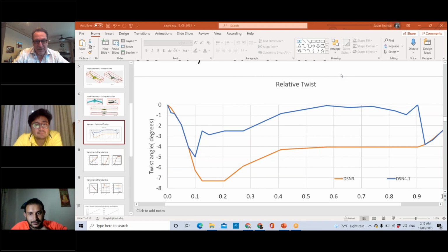It's also great because you've been able to now look at what it's going to take to do a rolling takeoff. And I'm not surprised at all that it's like 1,000 feet. That makes sense. When you make an airplane designed for this kind of endurance, the field length often is penalized a lot, which is also why these airplanes tend to be catapult launched so often. So that's good to know.